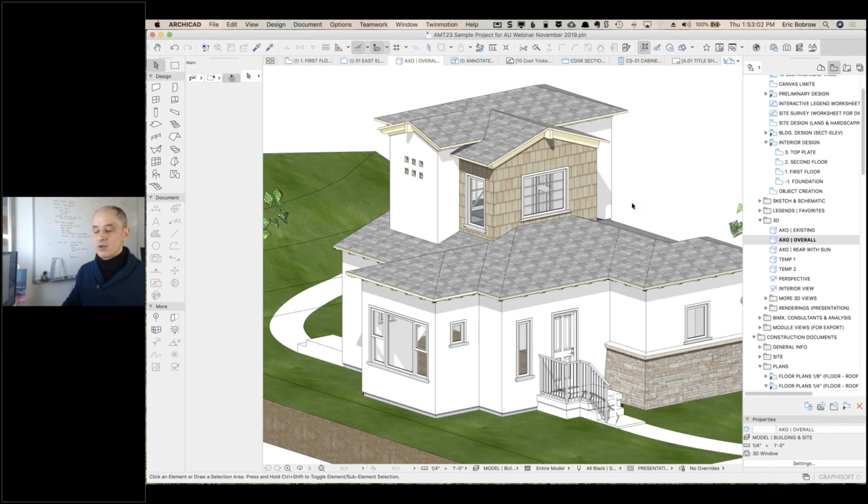Now, separate from that, you notice the lines on the roof edges, they're a little black. Well, there are different options here. For example, in the standard template, I believe both in the US and in international use, they would use the same set of pens that you would have on the plan. So in this case, GSNA, Graphisoft North America ArchiCAD View pens. When I select that, you can see these lines sort of disappear.